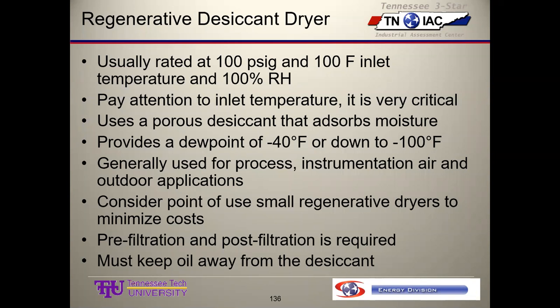For example, I did some work for Honda in Marysville, Ohio, a big plant, and we looked at the compressed air system, and they had desiccant dryers all over the place. They were drying air to dew points of -80 to -100 Fahrenheit because they were painting automobiles. And they were painting, what, 1,500 cars a day? 1,500 cars a day.